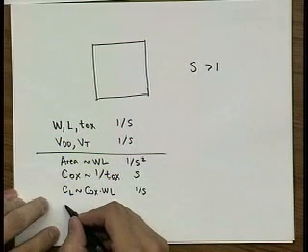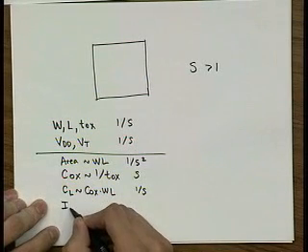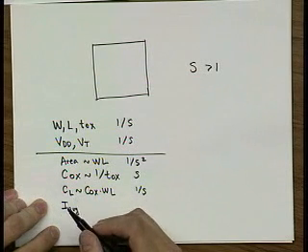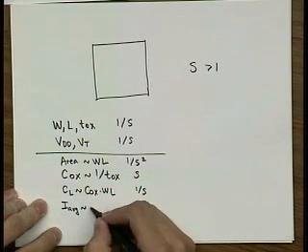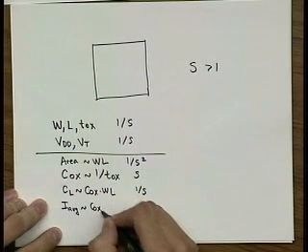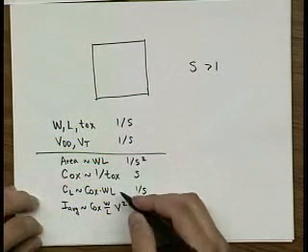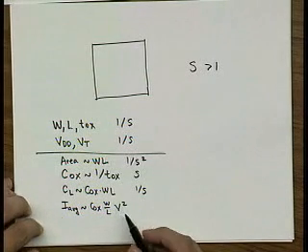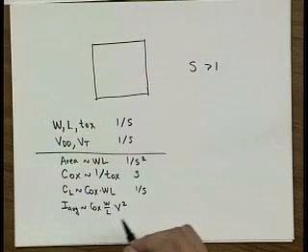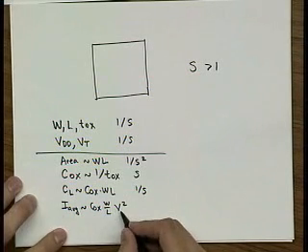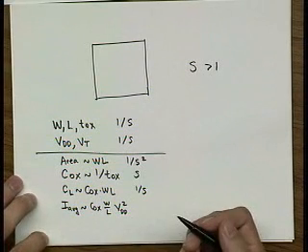Now, what happens with the average current? The current is proportional to C_ox, W over L, and voltage squared. Really, you have (VDD minus VT) squared, but since VDD and VT scale the same way, you can approximate this and say that's the voltage, scaling the same way as VDD.